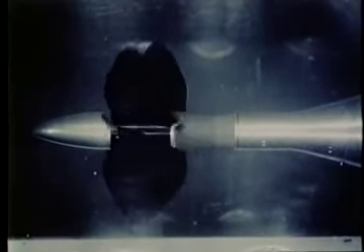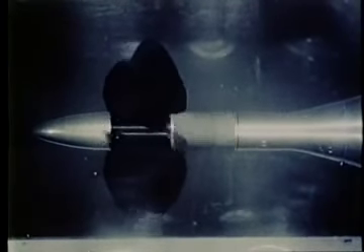The pressure is now being increased by raising the pressure of the gas above the water surface. The cavitation is reduced, and now it is almost suppressed. Incidentally, this procedure simulates the behavior of a cavitating submarine propeller as the submarine dives from a level near the ocean's surface.